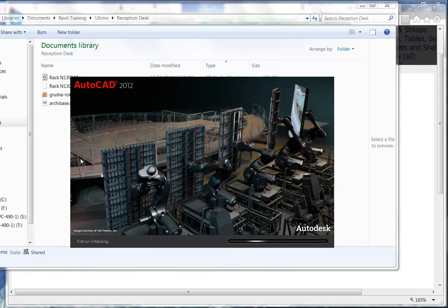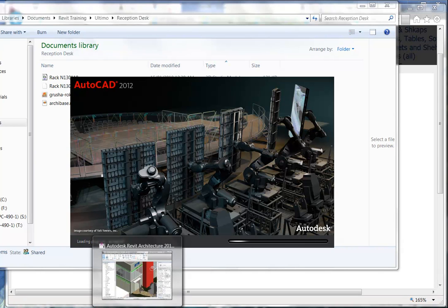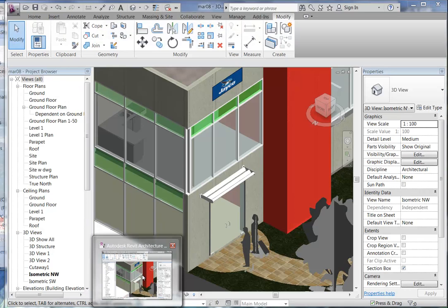But if you're not familiar with that, just use AutoCAD, and it's sometimes better than 3ds Max, or even after I bring them into 3ds Max. If I want to get them into Revit, sometimes I'll bring them into AutoCAD anyway, because the way it stores DWG files is a bit different, and to get it into Revit, usually you've got to make it a DWG. You can bring in SATs, ACIS solids, but they don't always work, so DWG is a good format to use.